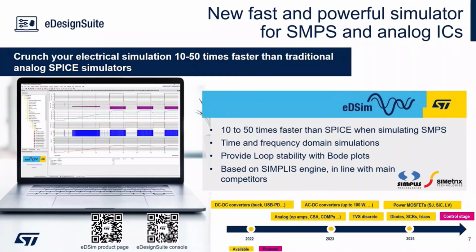This is based on SIMPLIS, which is created by Simplis Technologies, and this tool is 10 to 50 times faster than SPICE simulations for switch mode power supplies. I don't know if you've tried at some point, maybe during school, to simulate a buck regulator using PSPICE. It's painfully slow, and sometimes the simulation does not converge.